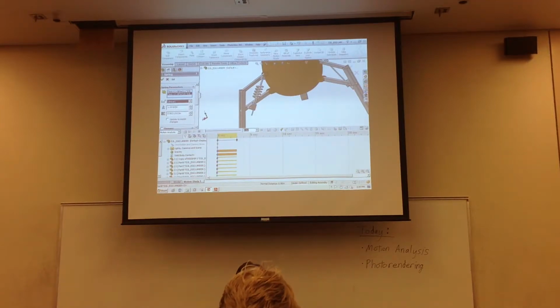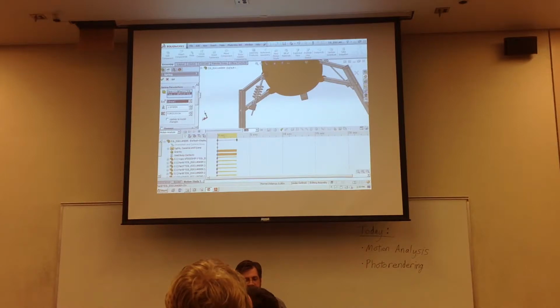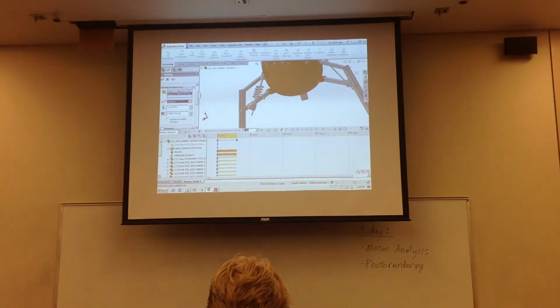We'll stick with that. This is the unsprung length, or the free length of the spring. And that's saying, okay, when you put this spring into position, is it already squeezed down so that it's like loaded and ready to spring something off? Or is it stretched out so that it's actively pulling on whatever it's supporting, whatever it's connected to? Or by default, it's going to use that link between those surfaces I clicked on to be the unsprung link, which means it's not loaded. It's just in a passive condition in there until something then compresses it or extends it.